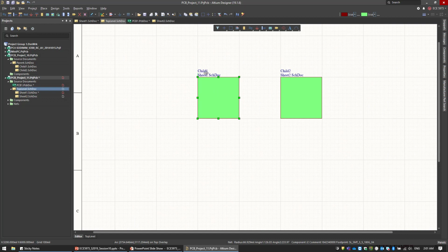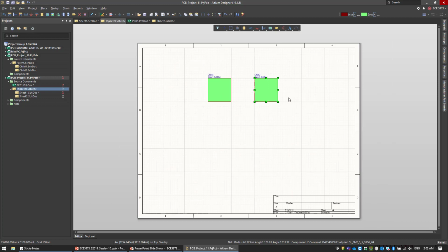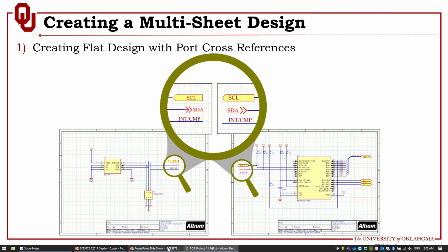It's just telling you that you have sheet number 1, and this sheet number 1 is for X function, and sheet number 2 is for Y function, and stuff like that. So just reference for you. If you have like 5-6 sheets, then you know that I have a sheet for LCD, a sheet for power, a sheet for microcontroller, and so on. Now it makes sense if you have more than 5 or 6 schematic sheets to go into the hierarchical design, not stay with the flat design, because it provides more meaningful architecture for the user.